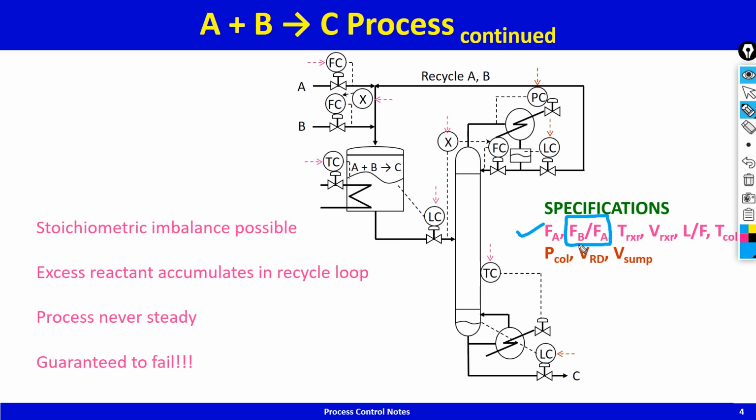So let us say you're running HYSYS or Aspen Plus, and let's say you specify this to be 100 kilomoles per hour, and let's say you decide, okay, let this be 101, and let us say this is 99.99% pure C. What will happen? The recycle loop will never converge because of this mismatch. Then you say, okay, let me be a smart cookie. I realize that there is an excess of B, and excess of B cannot be there. So let me say I'll specify this to be exactly 100, and exact values can be specified in a simulation.